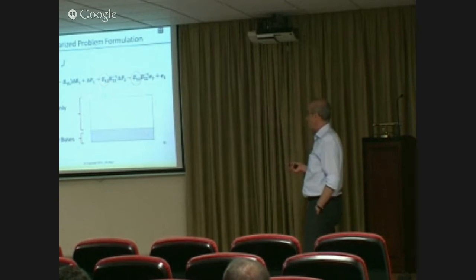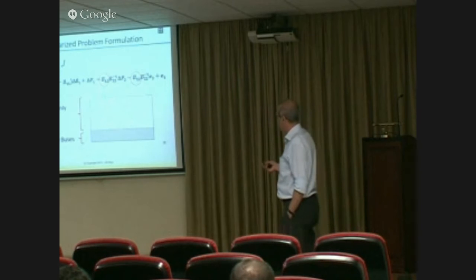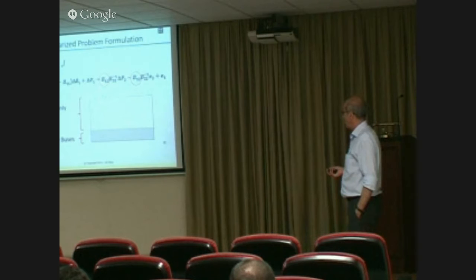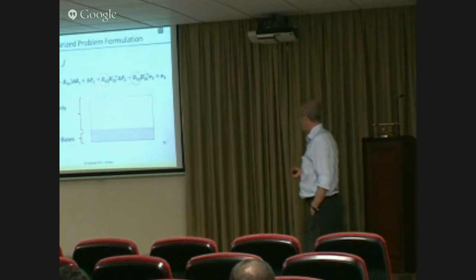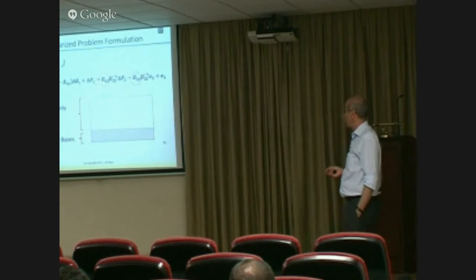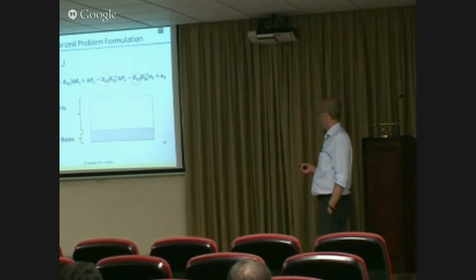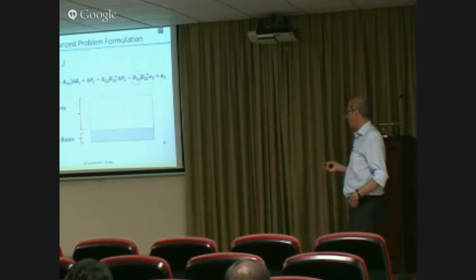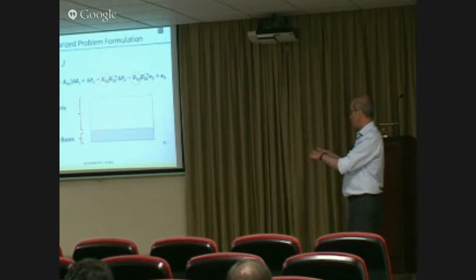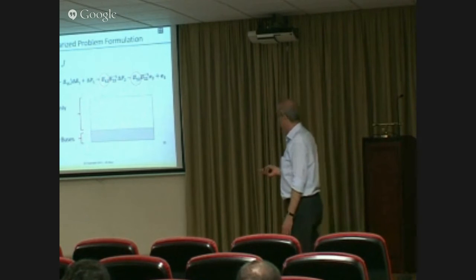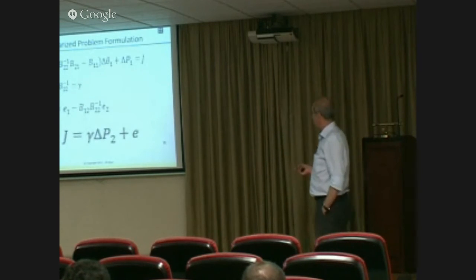Actually, it's almost empty because it will have zeros corresponding to the rows of the internal buses, and there will be only non-zeros along the rows of those corresponding to the boundaries. So even though it looks like a big matrix, it actually boils down to very few equations, and those are the ones corresponding to the boundaries of your internal system connecting it to the external system.